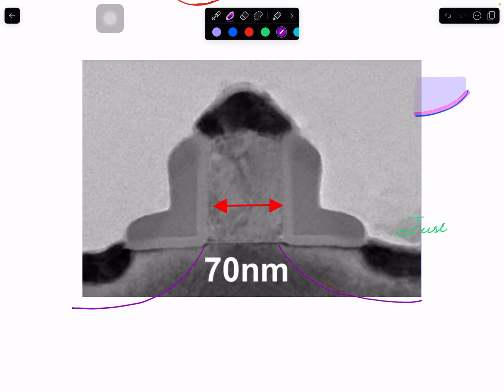What happens now? Initially what you do is you apply a VDD here. Supply voltage was made smaller with every process technology, but not at the same rate as the length. So the scaling in the supply voltage didn't come like this. It came more like this, because reducing the supply voltage has a big impact on the delay. So you don't want to get all the benefit of the delay improvement through reduction in the length and then waste it with this one. So instead it was brought down.